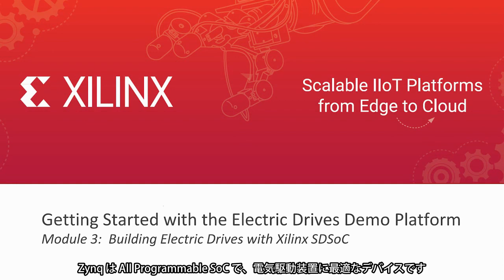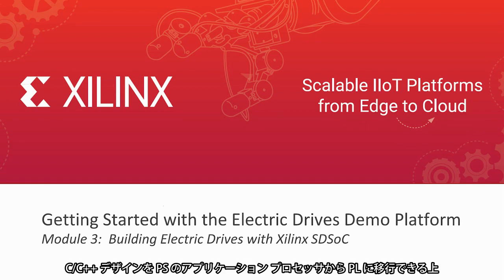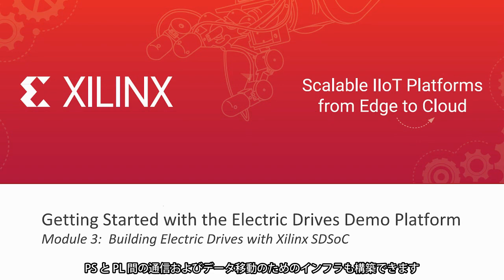As we've mentioned in previous videos, Zynq is an all-programmable system-on-chip produced by Xilinx and best in class for electric drive applications. SDSoC is a tool from Xilinx that lets you take your C or C++ based design and migrate some or all of the design from the application processor system to the programmable logic. And it builds the infrastructure to communicate and move the data between the two domains for you.